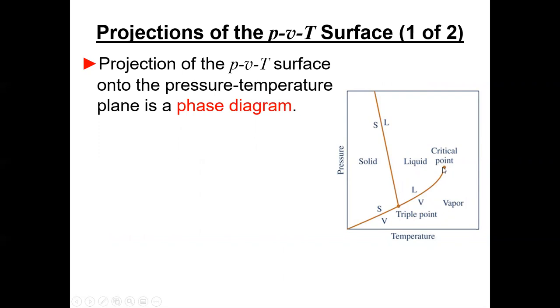So if that's the critical point in this plane, then as you do a transition, say we did a constant pressure and increased it up to this point, then at that point where you hit that liquid-vapor line, you're going to come into or out of the plane of the paper, whichever way is positive. As you come across the dome, I guess you would probably come towards us, increasing volume, and then once you got across it, you could continue out into the vapor side. So there's a three-dimensional aspect to this, and you have to kind of think about it.